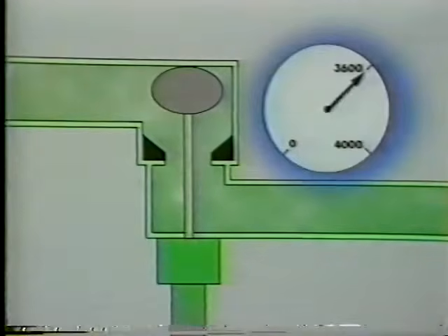This simplified illustration shows a cross-section of an intercept valve and the steam lines leading into and out of it. This line connects the intercept valve to the reheater, and this line connects the intercept valve to the IP turbine. We're also including a gauge that measures turbine speed in RPM. Right now, the turbine is at normal operating speed, and the valve is fully open.